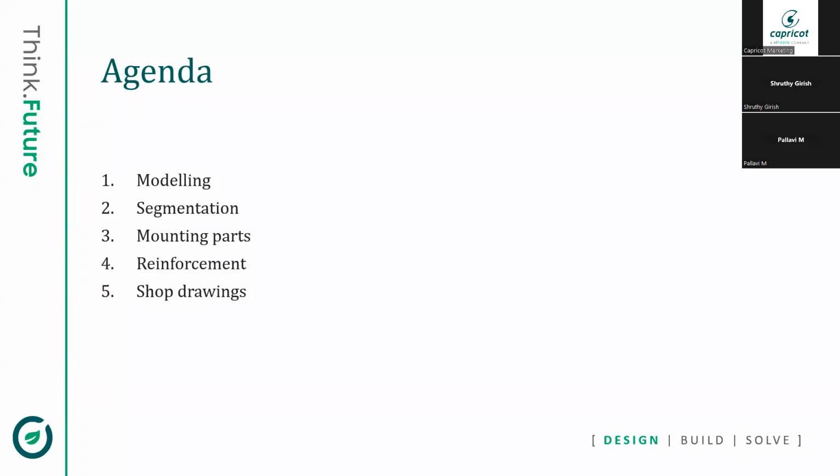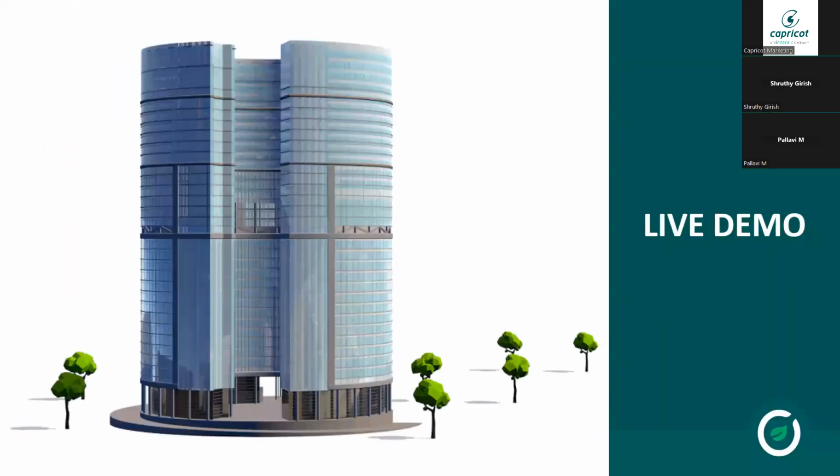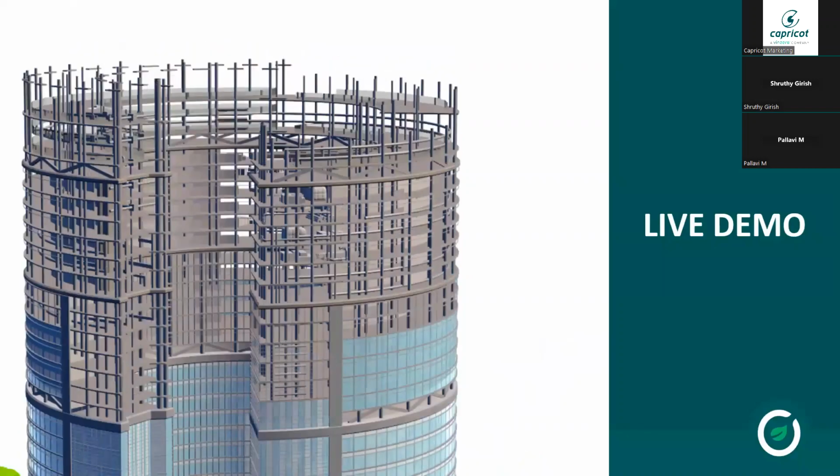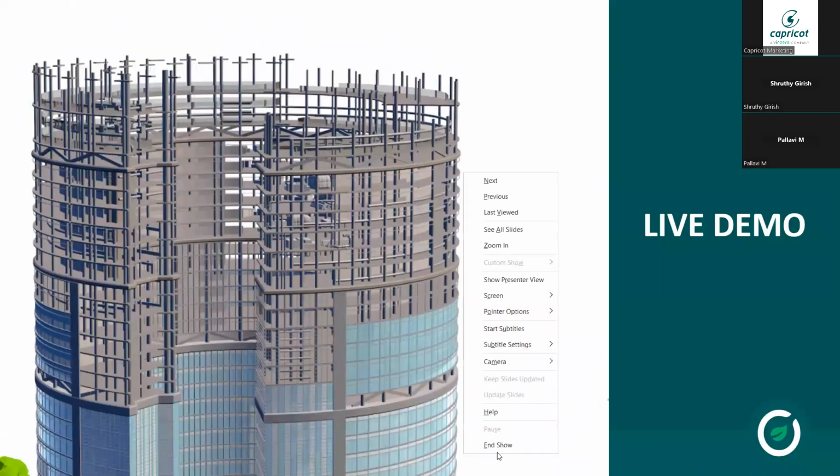For today's session, we'll be discussing modeling, segmentation, mounting parts, as well as reinforcement and shop drawing. So we'll be covering all 5 parts of the precast extension for Revit. Let me just start with the project.